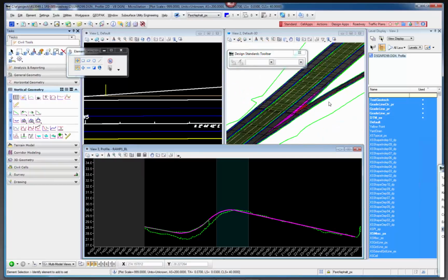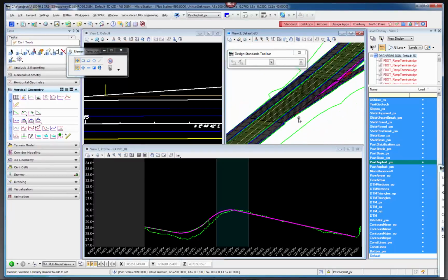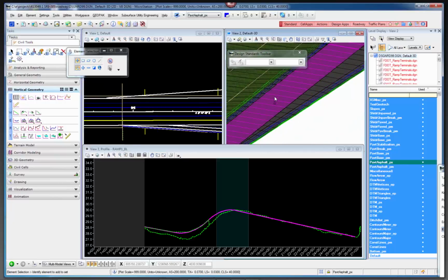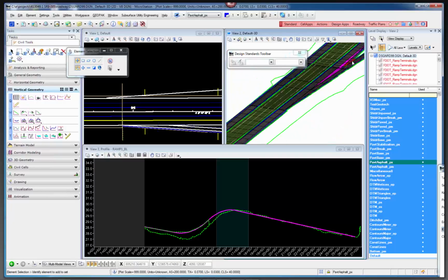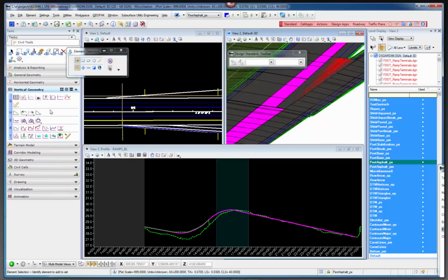Now there's a ramp corridor out here, that's in one model, but all along here with my transitions, my horizontal reference lines, basically pulling these out according to the template slopes, what I can do is get a basic preliminary profile of where that would be if it was at a 3% slope, and then if this was at a 0% slope, I can pretty much establish this 3D line all the way up to the end of this physical gore.